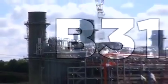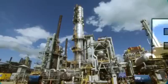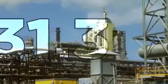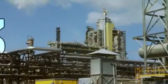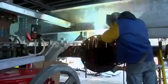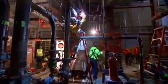B31.1 is for piping typically found in power generating plants and industrial facilities. B31.3 is for piping typically found in petroleum refineries, chemical and pharmaceutical facilities. B31.5 is for refrigeration piping, and B31.9 is for building services piping. B31.4 and B31.8 are for pipelines that transport liquid hydrocarbons and gases. These B31 code sections require the owner, usually with the assistance of his engineer, to select the appropriate code section.